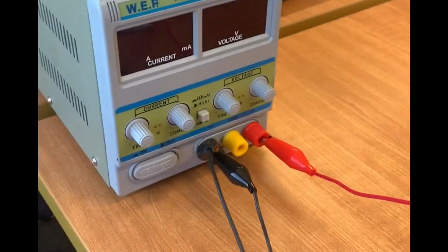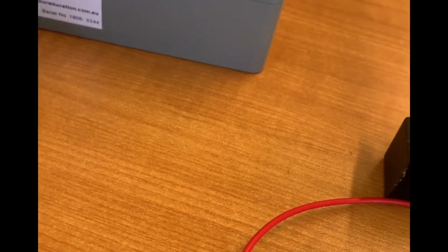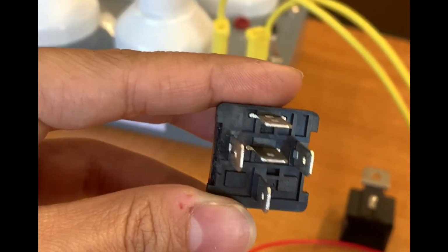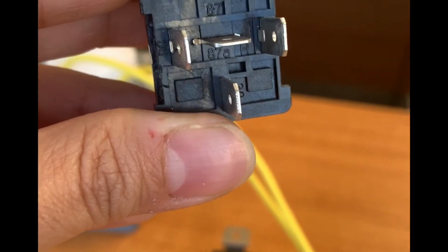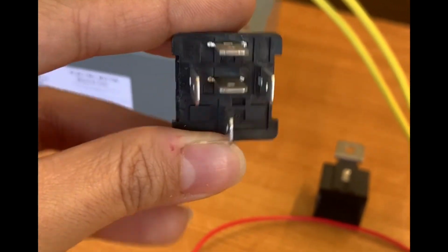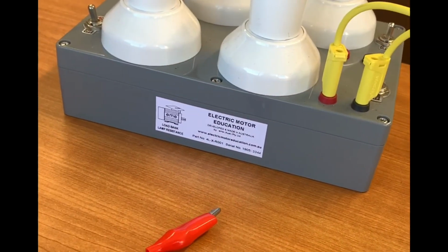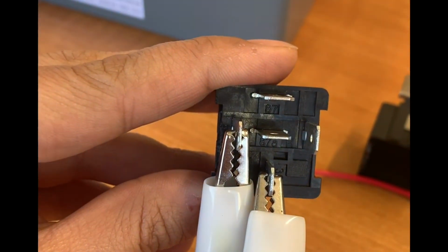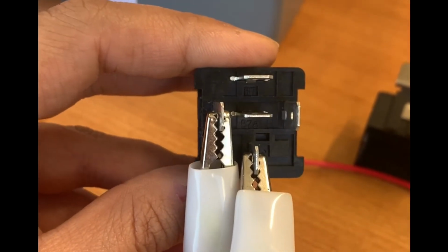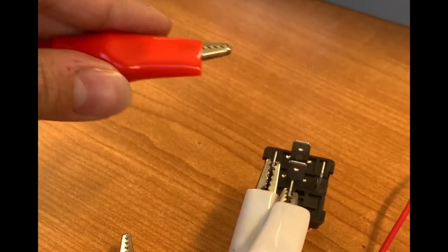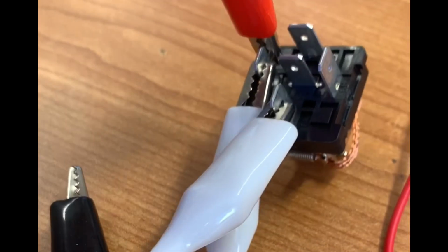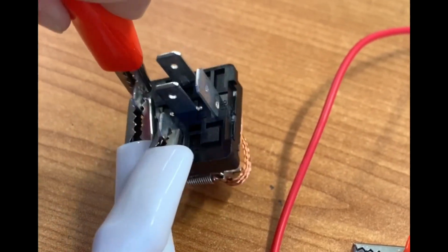It's a simple demonstration of what is happening in the car. Positive from the power supply, as you see, and I'm going to connect it with these two coils that are bringing the power in. So 86 and 30, right? So first I'm going to connect these two together because they are both going to get the power in, and then I will connect the red alligator clip, which is positive, to that. As you see here, I have connected 30 and 86 here, right? Now I'm going to connect this as a positive side. We're bringing the power into the switch.